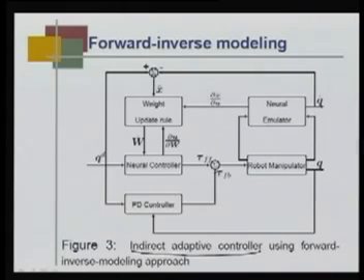This neural emulator has the capacity to exactly mimic the behavior of the robot manipulator, not only in terms of the desired target, but given the desired target, what is the desired input. So, in both ways this is an ideal neural emulator. This is our desired trajectory QD. Given this desired trajectory, here is my neural controller. I have a two stage controller here. The neural controller actuates the feedforward torque, and the PD controller actuates the feedback torque, and together they are applied to the robot manipulator.